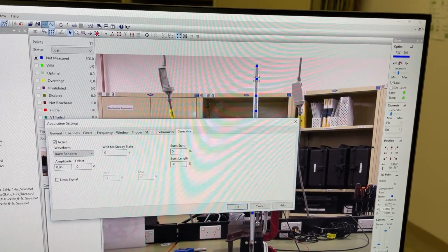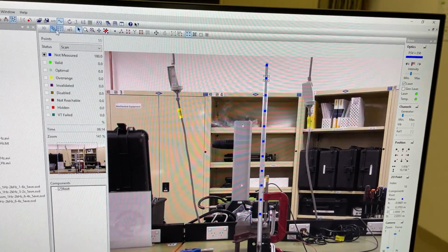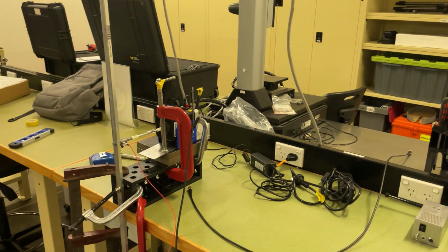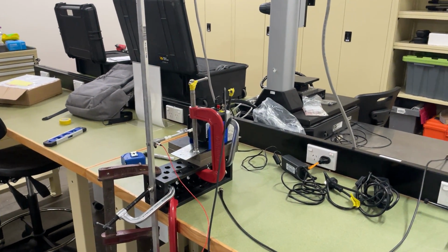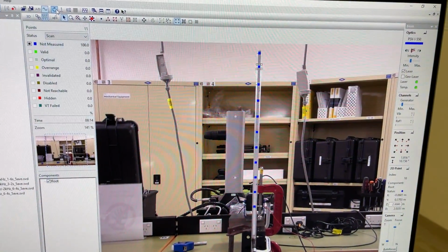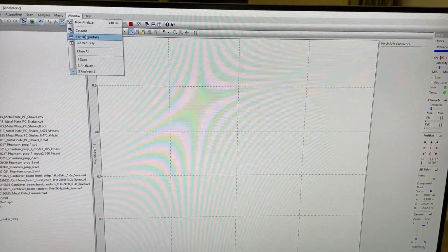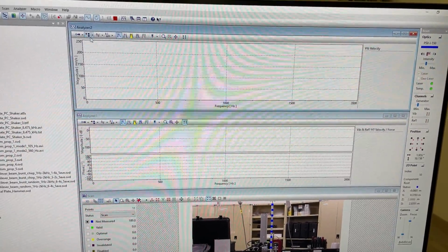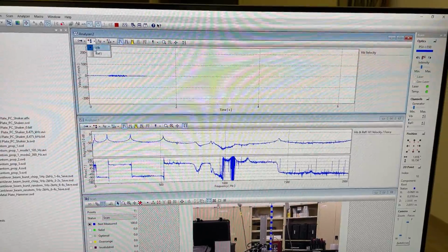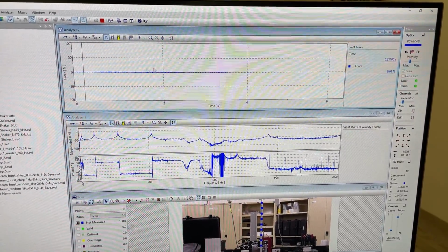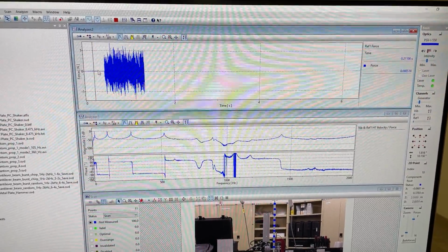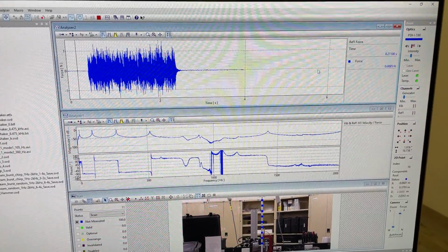So if I click burst random and hit the OK button, now you can hear a different type of measurement, a different type of excitation, a burst random signal. Okay, in the measurement window, if I tile these and we have a look at the time domain reference, this is the force transducer. You can see that that's a burst random signal here. So this is the burst, this is 5%, it ends after 30%, and then the energy decays.